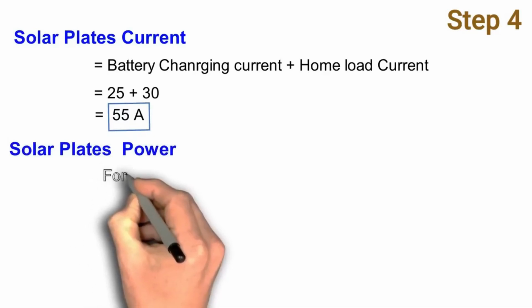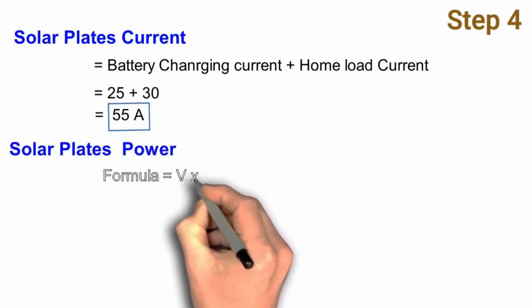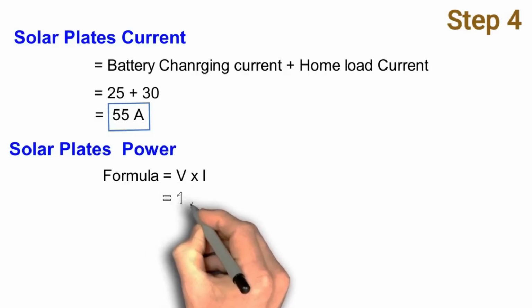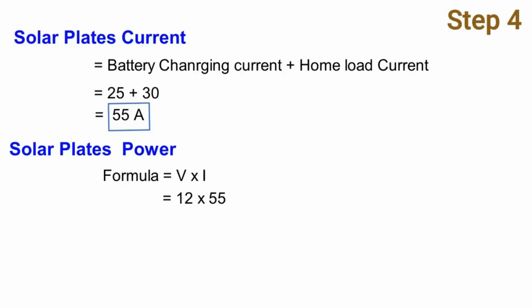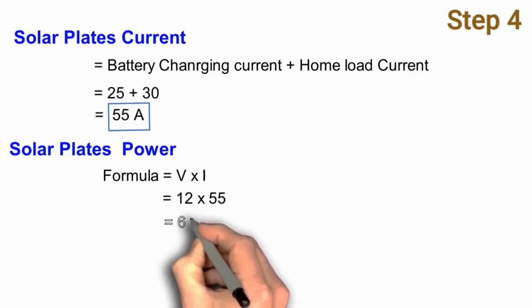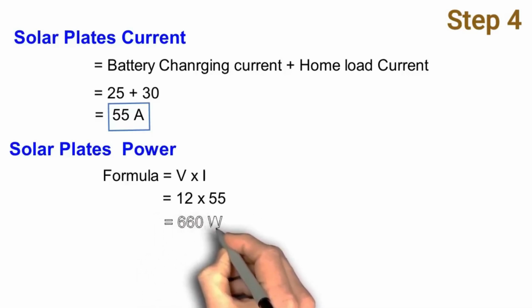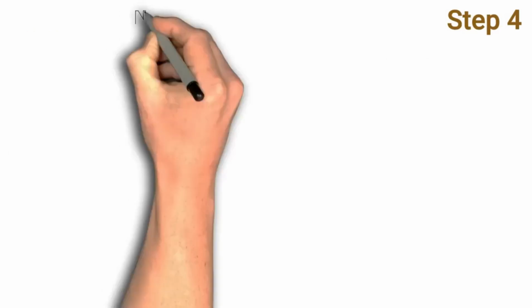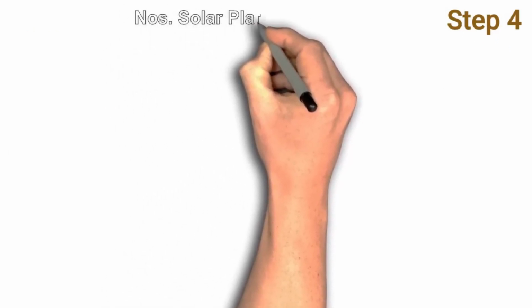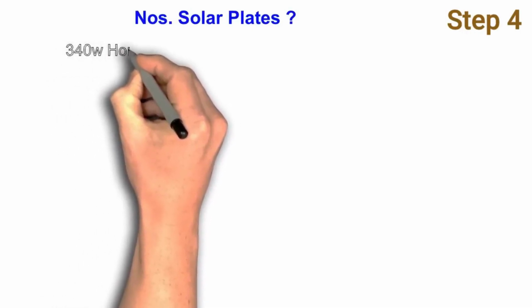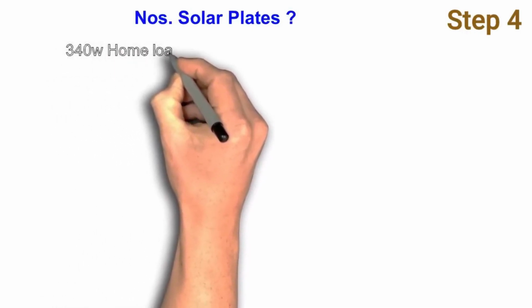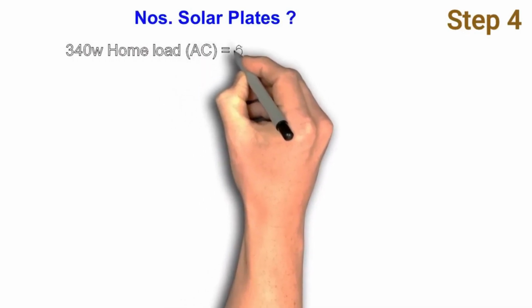Once you have all the information, you can select the right solar system components for your home. Ensure that your inverter, battery, and solar panels are properly matched to your energy needs. For example, if your total home load is 3,500 watts, your solar panel system should generate enough energy to meet that demand. And the battery should store enough power for backup. The inverter should be able to handle the peak load without any issues.